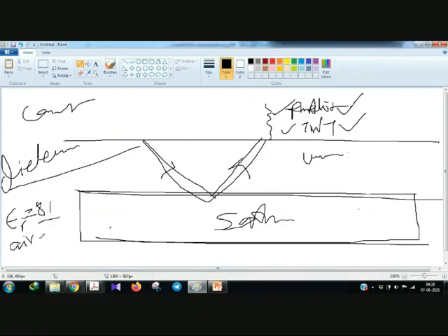Air has epsilon r equal to 1. So when it's saturated with water, epsilon r2 will be greater than epsilon r1. So there is a contrast here, and this water table will appear as a high amplitude signal.